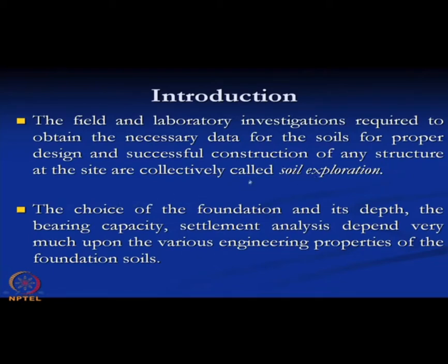The choice of foundation and its depth, the bearing capacity, and settlement analysis depend very much upon various engineering properties of the foundation soils. So, we should know the various engineering properties of the foundation soil before we start the design of the foundation. As I mentioned, the strength properties, that means c and phi, are very important properties for foundation design.